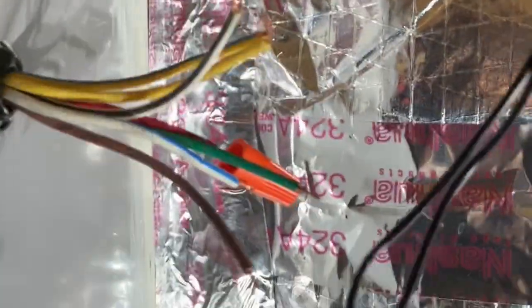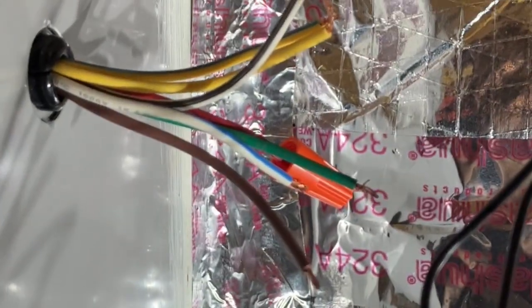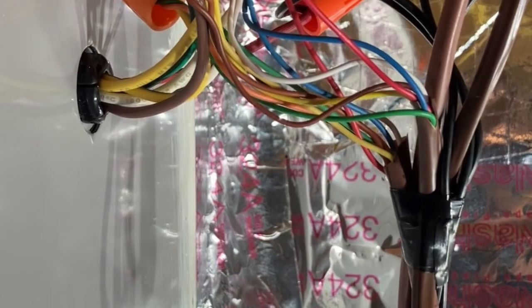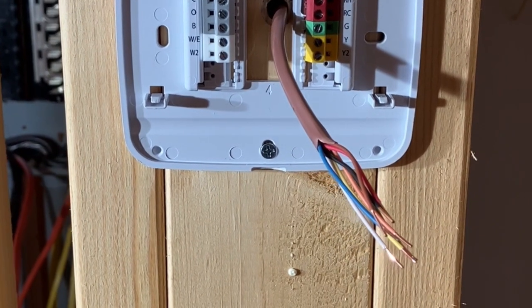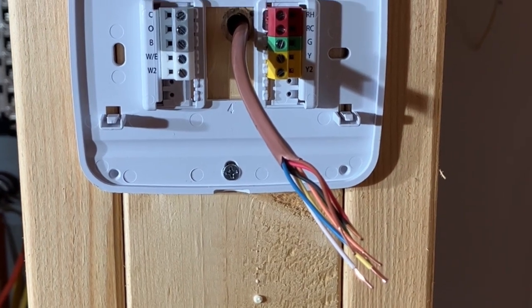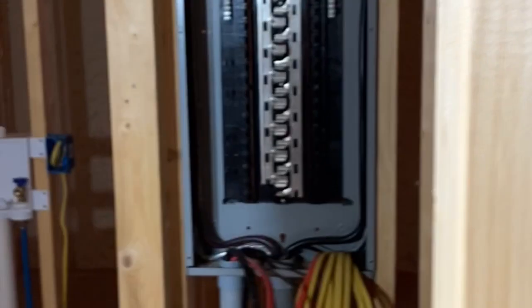Just got to make them all up right here on the unit thermostat wires according to what the book says. Thermostat wires all hooked up, and double check them on the outdoor unit, make sure all the colors are right, and then we're gonna put some breakers in and give it a try. Gotta put thermostat wires on, program the thermostat, and get the breakers in.